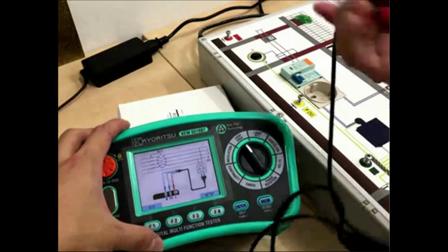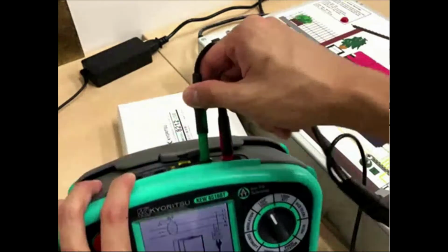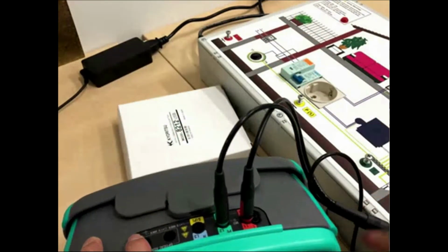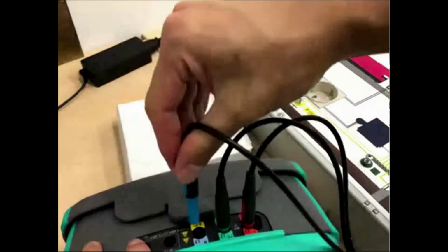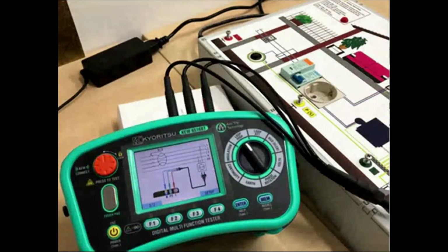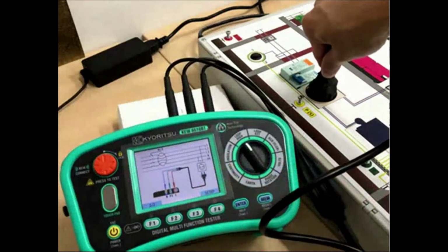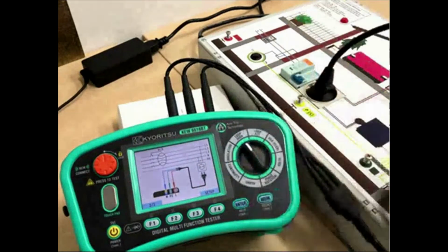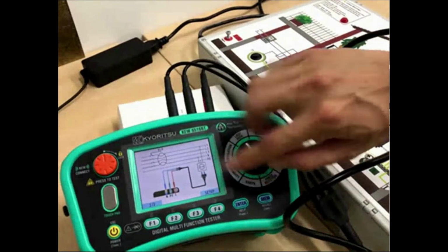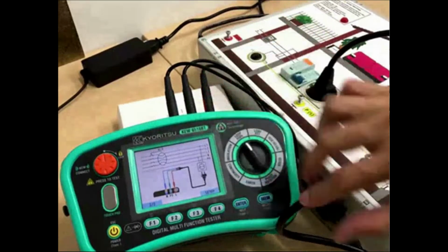So I connect red to red, green to behind here, live to live, earth to PE. Understand? Then blue to neutral. Then we put it back. So this one connect to here. Then okay, just now I mentioned to you the insulation test, continuity test, earth test. We don't need live wire. We don't need power supply. But loop testing, we need power supply.